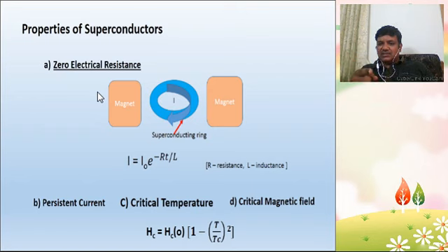That is a very crucial thing: an external magnetic field is not required, the internal magnetic field itself destroys it. That effect is called the Silsbee effect, which was found in 1916. It gives a relation between the critical current and the critical magnetic field, where Ic is equal to 2 pi R into Hc. So this graph indicates the relationship between current density, critical magnetic field, and critical temperature.